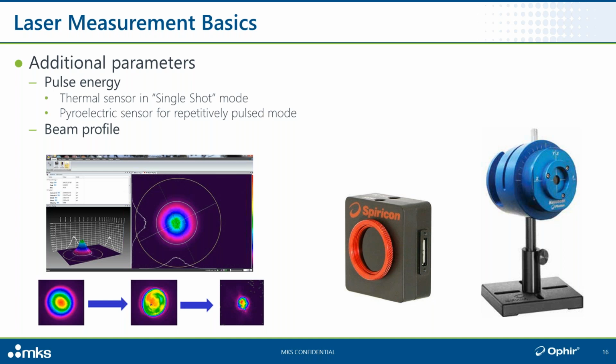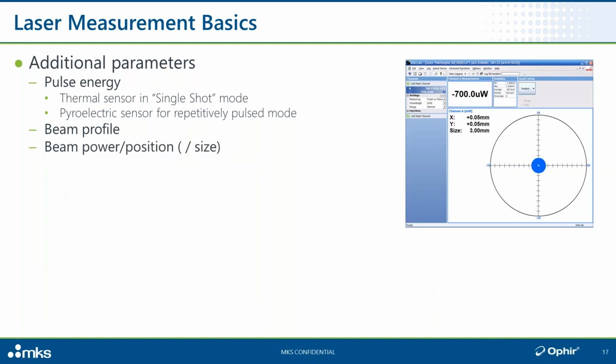In many applications, the spatial profile of the beam, which means the spatial distribution of energy in the beam's cross-section, can be critical. It affects the focusability of the beam, if I can coin that as a word, and the shape of the focal spot, and therefore the shape of the resulting cut, hole, weld, zap, or whatever. As you probably know, we have solutions for beam profiling of high power beams way beyond the scope of today's discussion, but I just had to mention it.